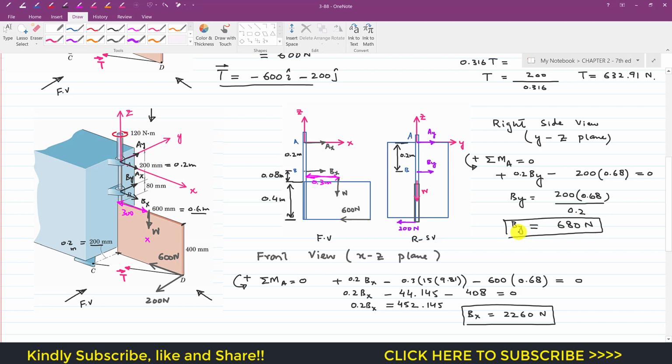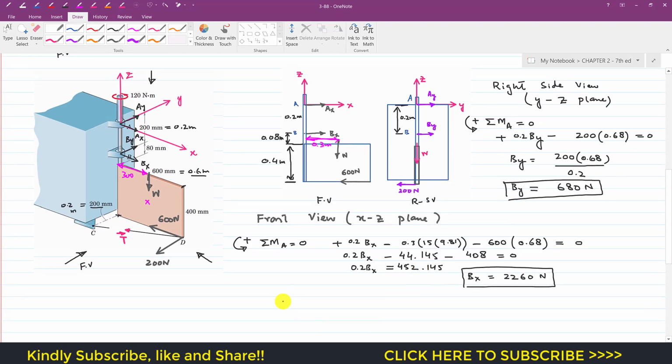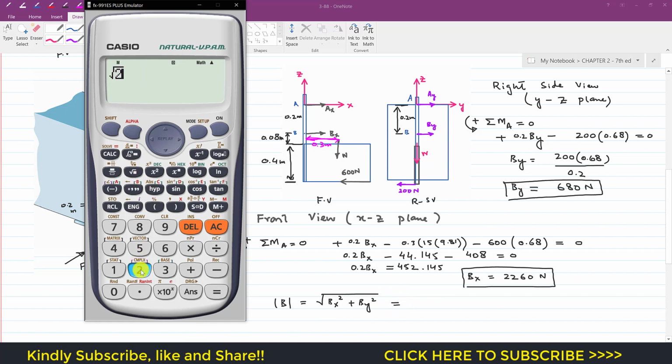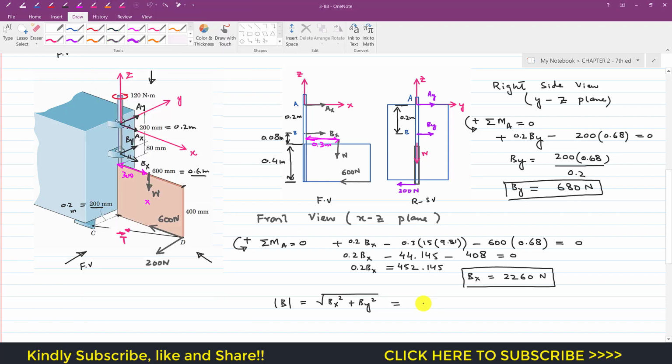So the total resultant reaction at point B will be equal to the square root of Bx square plus By square. So this is equal to 2260 square plus 680 square under the square root. This gives us approximately 2360 newtons.